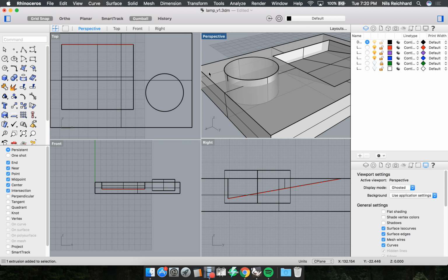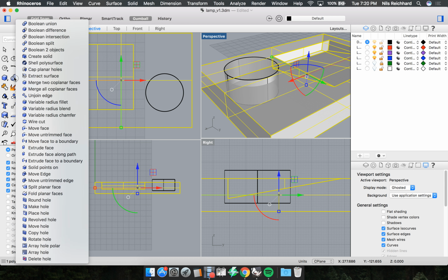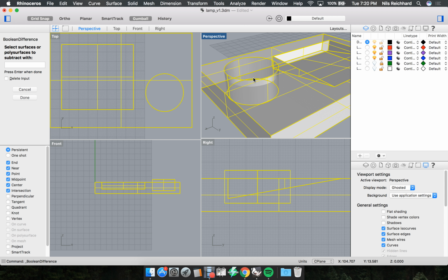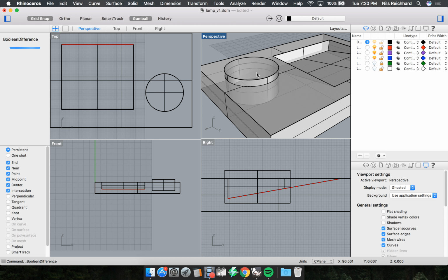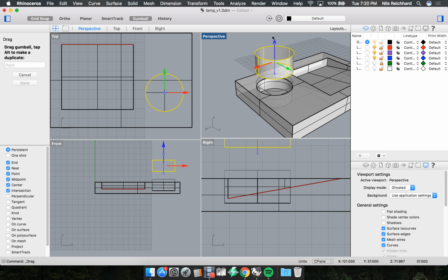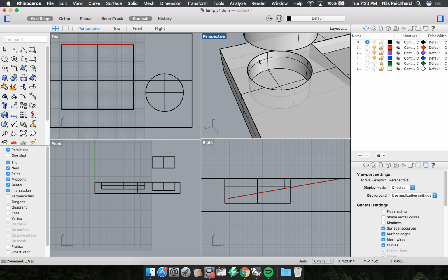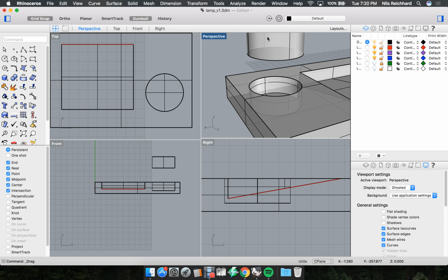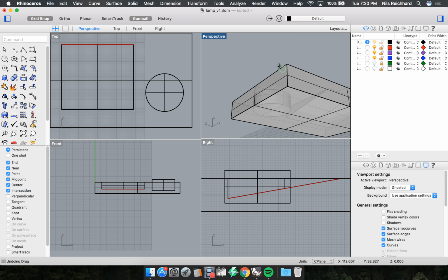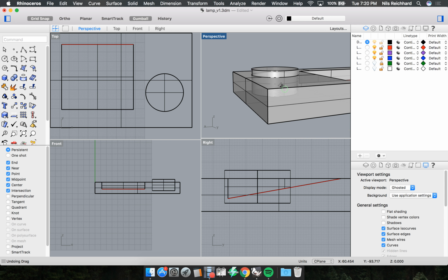What I'll do again here is Boolean difference. So I'll select Boolean difference, and I already have selected this object, so it's going to tell me which object you're going to delete. Subtract with, and I will select this cylinder. So now what will happen is that I will have a little, how to say, intrusion, or maybe just an inner cylinder where this one fits in, and it doesn't cross to the other side. So in real life it could work out.